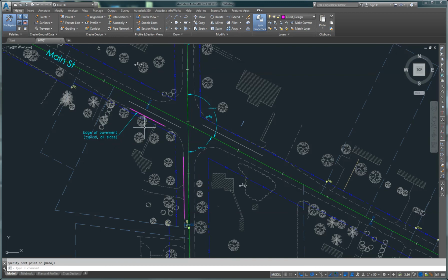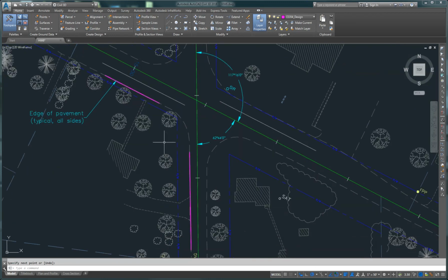If you look in the table that we're going to be looking at, it says there's an offset and a radius and a taper. And so the first thing is look at that offset. Let's say the offset in the table is 4 feet. And so I'm going to offset these lines back 4 feet. That's what that kind of means. You'll see here when we're done how it all works. So this is the offset command in AutoCAD. It looks like this. I'm going to click that. Down here at the bottom, it's going to ask you questions and tell you what it's doing. And if you look just to the lower right of the crosshairs, it asks you questions and it'll tell you what's going on.